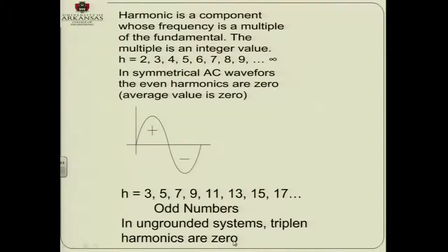If you see a second harmonic, it's in a single-phase system. If you see a third harmonic, it tells you that there is a single-phase load. Why am I saying this here? This probably needs to go to the next chapter, chapter 8, since I've been talking about it.